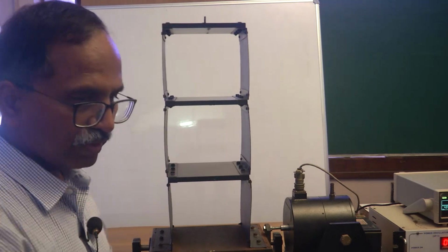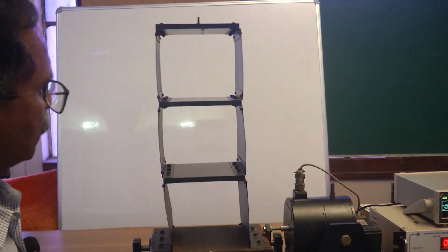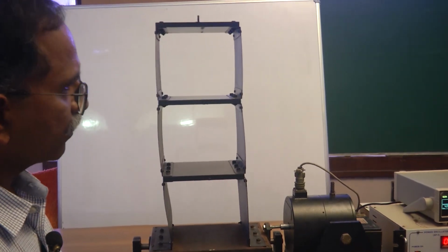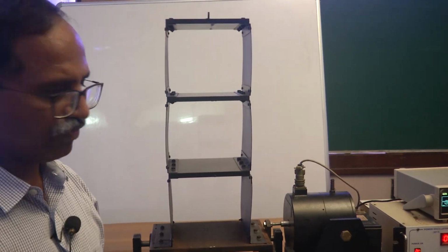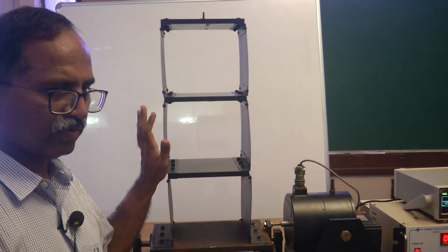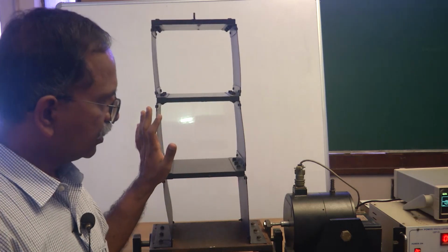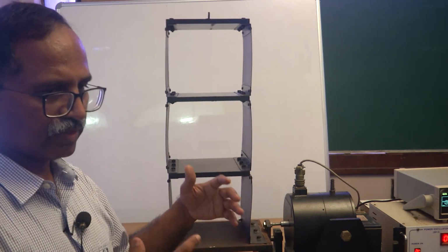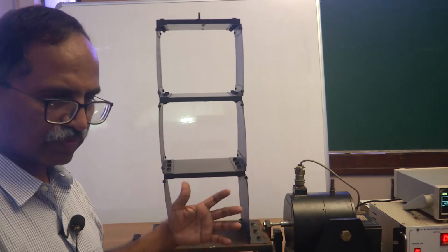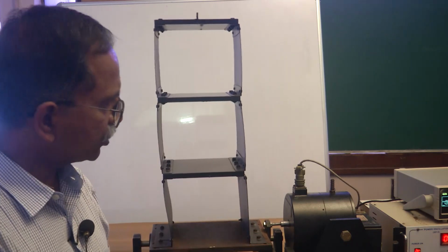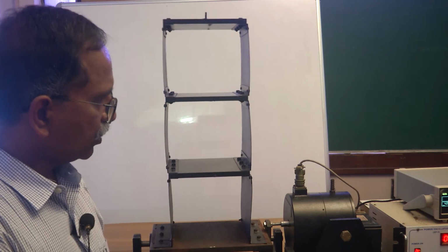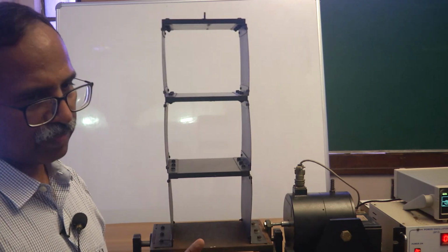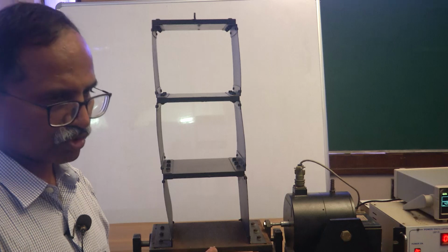So this is how the vibration absorber works for a multi-degree of freedom system as well. What we have learnt in this experiment is that we have seen the mode shape in action. It is not by exciting the vibratory system with an initial condition matching the mode shape and observing the subsequent vibration at the natural mode, but by exciting the system at its resonance.